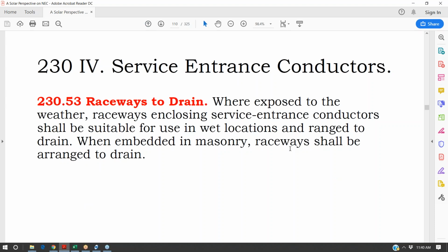Where we do this is when you're on a rooftop and you have your solar cables going into the rooftop. The rooftop's already slanted. If we have a junction box on the roof for our cable transition, we go into the bottom of the box at the bottom of the slant.